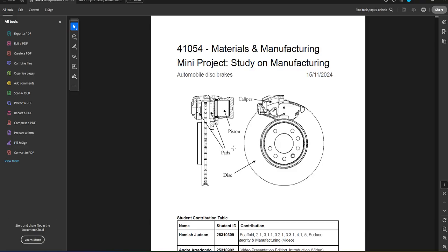Powder compacted and sort of sintered, or just using some of the adhesive to compact the pads that can be fixed on the plate, and the plate will be sitting in between the piston and piston 2 sides within the caliper, and the disc will be in between. This itself is usually done by the casting process, and it's going to be machined to the shape. Usually they don't machine directly from a cylinder because the casted part is going to have a higher resistance to the thermal changes. Okay, so that's the disc, that's the flange.